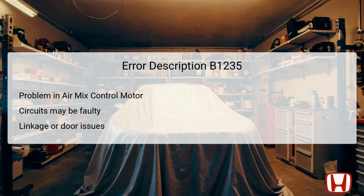DTC B1235 or code 42 signifies an issue with the air mix control motor or its associated circuits, linkage, or door. This motor is fundamental in controlling how much heated or cooled air enters the cabin. If the circuit is faulty, it can lead to intermittent operation or complete failure of the temperature control system.